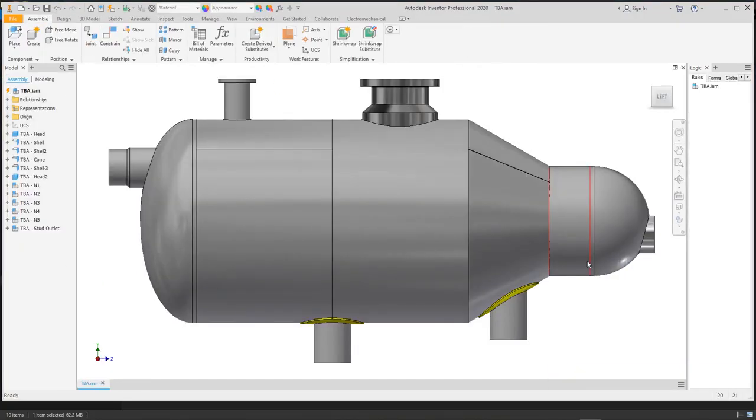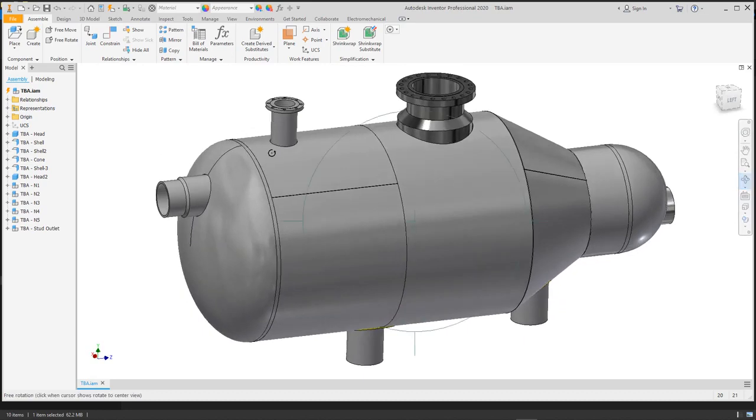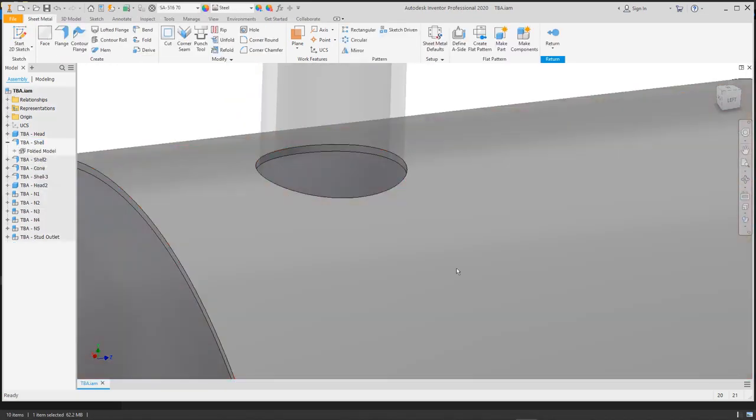The second question was, there is no bevel edge preparation option in the shell and nozzle joint. Actually, those options exist in Autodesk Inventor itself. The welding preparation and welding options, like adding a fillet weld, groove weld, all of that, you can do by using Autodesk Inventor.